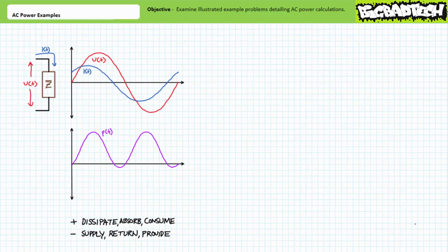While calculable by individuals well-versed in math and with ample amounts of time on their hands, the specifics of the instantaneous power function are of dubious utility, and users often content themselves with average behavior over time. Given the time-variant power function is symmetric in nature, one can draw a horizontal line running right through the middle of it, where this horizontal line can be thought of as the average power figure. In this hypothetical scenario, our average value, whatever it might be, appears to be above the horizontal axis. This makes perfect sense, given the longer and larger periods of positive power seem to outweigh the somewhat briefer and smaller periods of negative power.